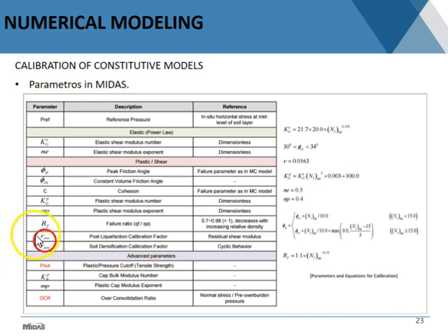But the idea with these two in our case is that you can use those to calibrate the results of whatever test results you may have from the lab, and you want to achieve a good match with whatever you have in the numerical model. You can go ahead and modify this a little. Of course, you can modify more than that, but these two showed to be useful in that sense.